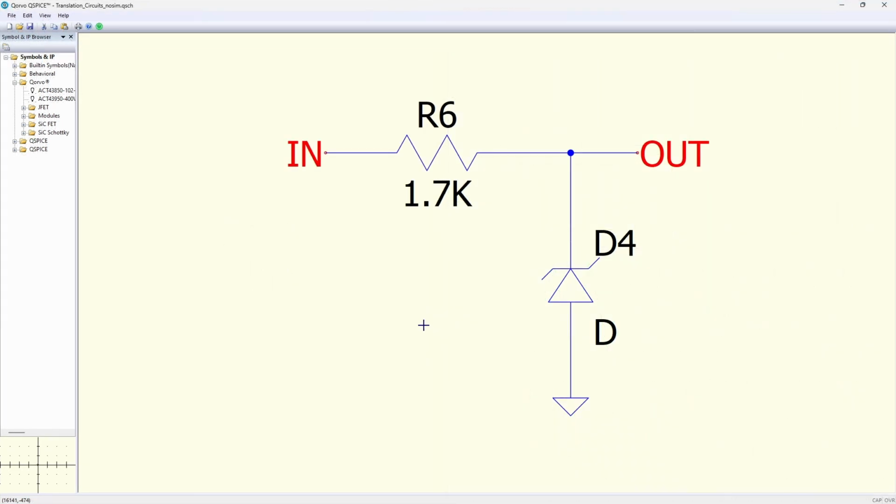Similar to the LED, but with more variety in voltages available, is the Zener diode. A Zener diode is designed to be connected up in a reverse polarity. So now, whenever the voltage reaches a certain level, it's going to activate the diode in reverse and allow current to flow through it. The diode will naturally regulate to its reverse breakdown voltage.